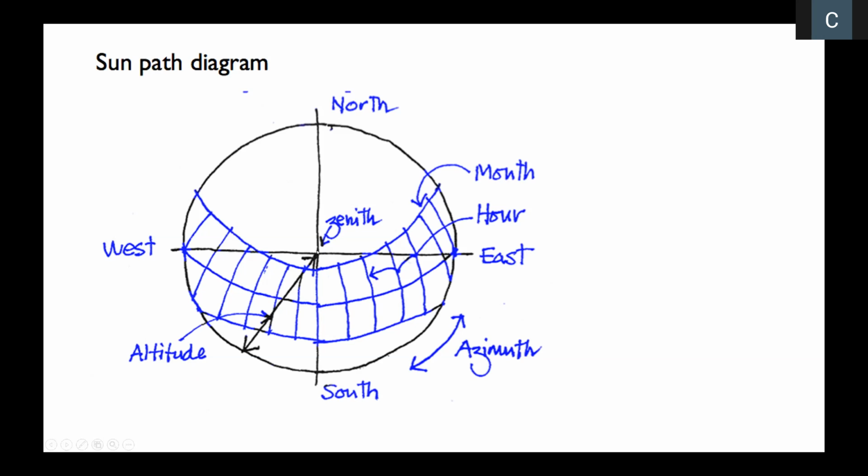That point of interest, you can think of it intuitively as if you were taking a photograph from a place, right? You have to choose a specific spot to put your camera. Well, you're putting the camera right here for this sun path diagram and pointing it directly up, and you've got just the right fisheye. You could produce, in fact, a view that would show the sky having a horizon here and the zenith directly overhead. And if you were to leave your camera there and do a stop motion, you could see the sun as it traveled from east to west every day along a line, and it would always fall within this sun path area.